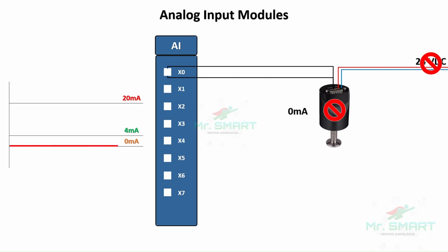The sensor is not able to produce any minor currents and the input terminal of the PLC now receives 0 milliamperes as input. So, now we can easily distinguish the no measurement state and the faulty state of the device by scaling it to 4 to 20 milliamperes. This is the major reason why the analog signals are scaled from 4 milliamperes instead of 0 milliamperes.